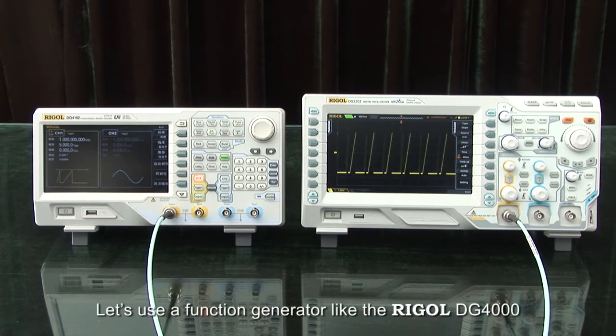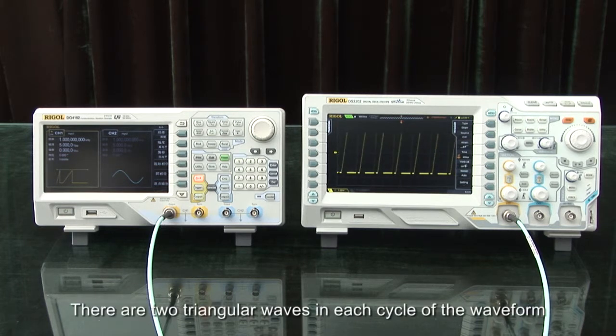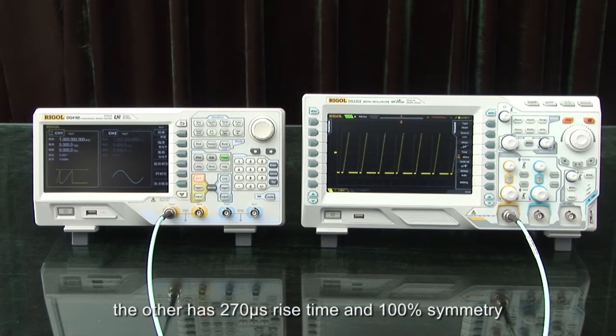Let's use a function generator like the Rigol DG4000 series to output an arbitrary waveform with a 5-volt peak-to-peak amplitude and 1 millisecond period. There are two triangular waves in each cycle of this waveform. One triangular wave has a 90 microsecond rise time and 100% symmetry. The other has a 270 microsecond rise time and 100% symmetry.